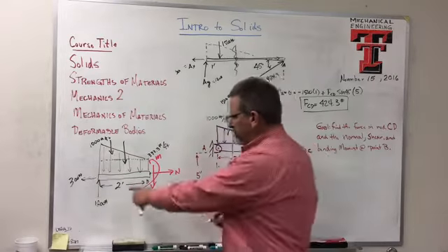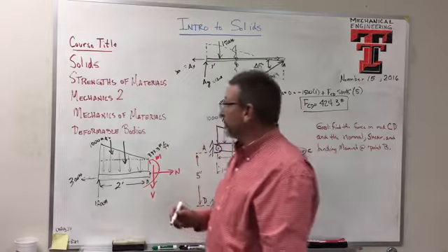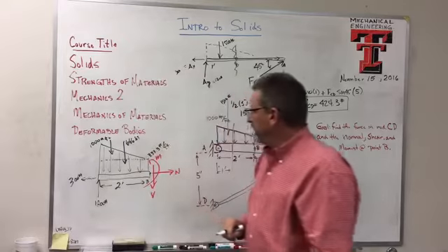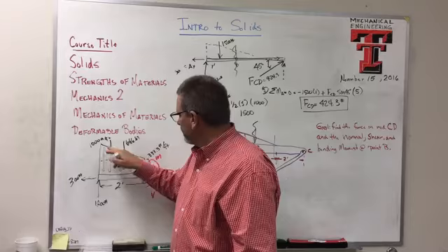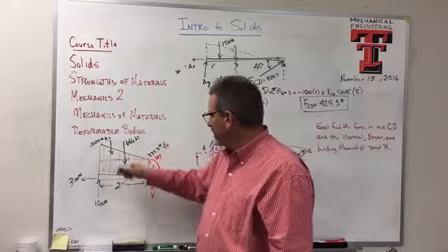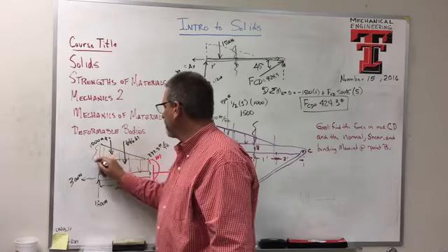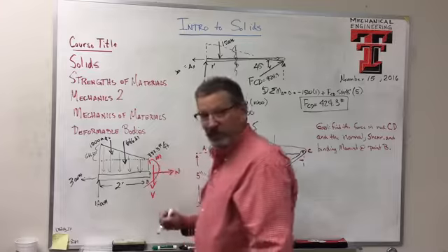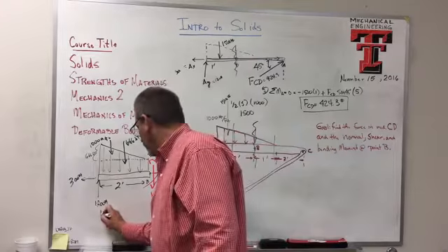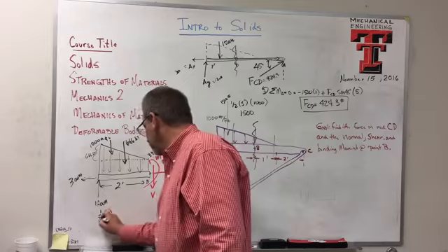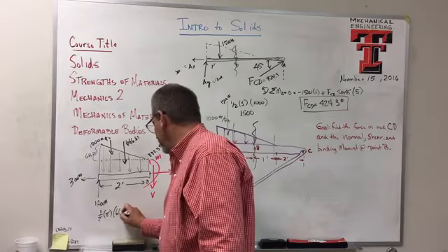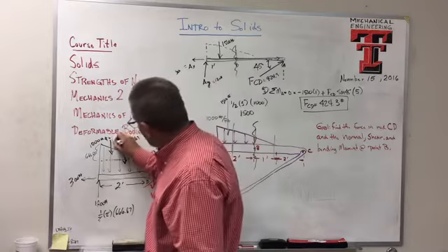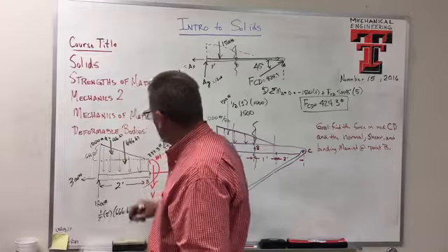So the rectangle is 2 times 333.3, which is 666.67. And then it's 1,000 at this end over here, right? So what's this height here? Well, this height here is 666.67, right? So the area of the triangle must be 1/2 the base times the height, right? So this over here also is 666.67 at a third, right?